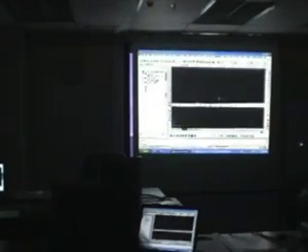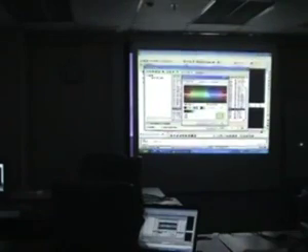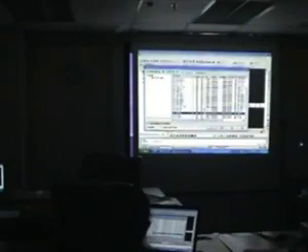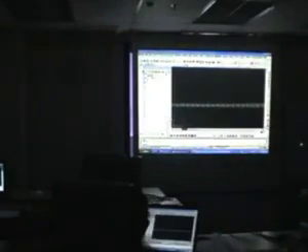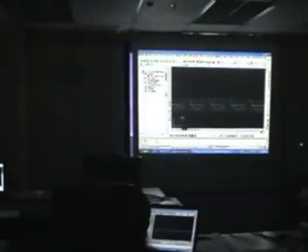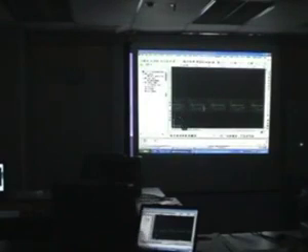Okay, let me adjust the color of the layers. You can see again they've got their own layers. So OGL, I'm going to put it as green. My PL, I'm going to put it as cyan. And the grids, I'm going to use dark gray. So this is easy to see. So you can actually see the sections. So you can use this for plotting. This is for the section drawings.